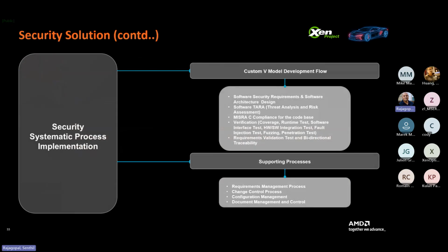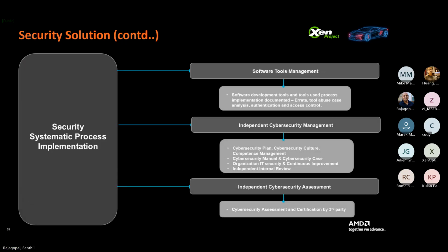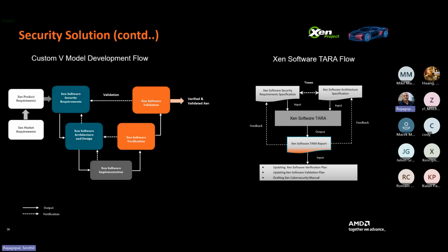We will have a similar process to how we did automotive safety, with separate activities to meet ISO 21434. The same flow follows, but differently. We're trying to model the safety critical V model development to security critical. We have FMEA, failure mode analysis, in safety, and we have TARA, threat analysis and risk assessment, which is something similar to failure mode and effects analysis.